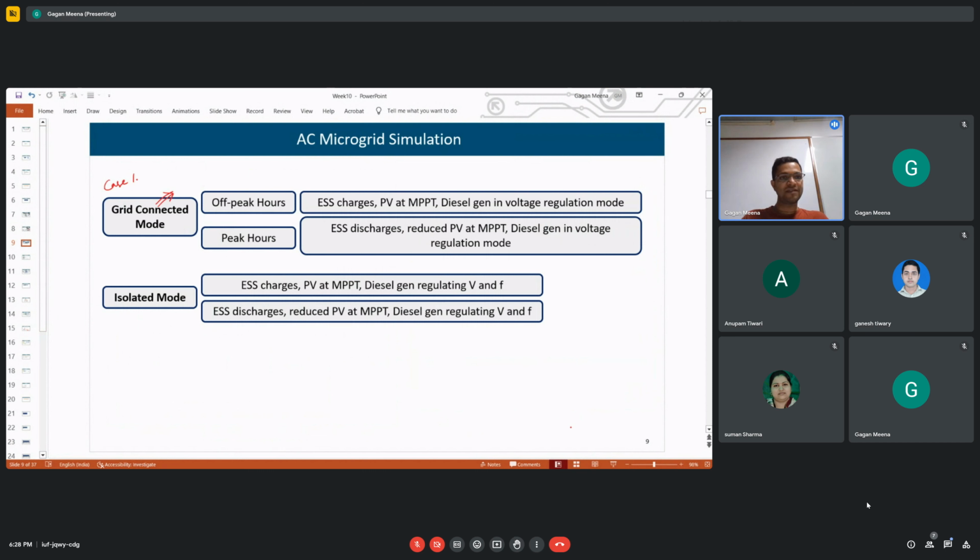Okay. So here the diesel generator will supply the load as well as charge the battery. If the output of the diesel generator is less than P_L minus P_G, the diesel generator cannot do anything here because its output is less, then the battery will come into the picture.